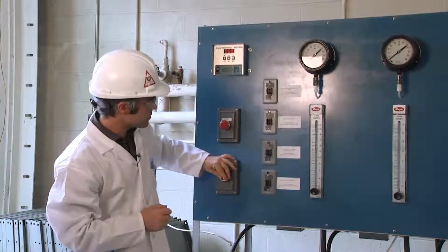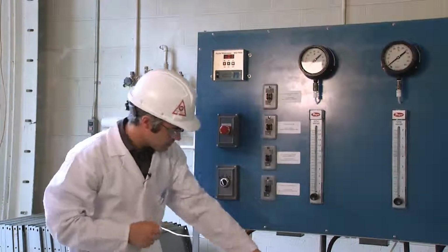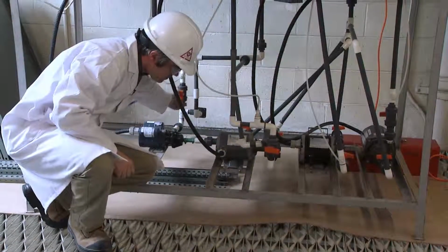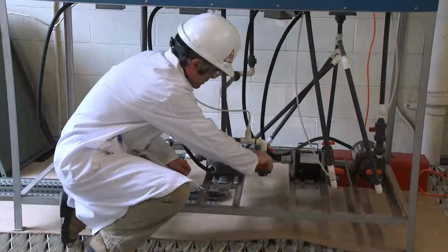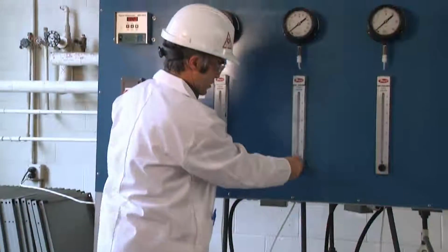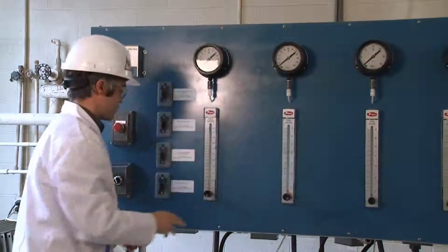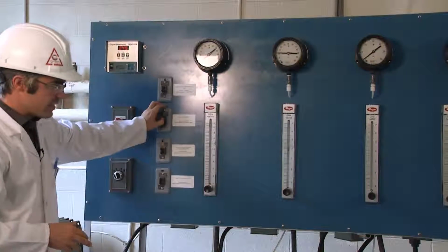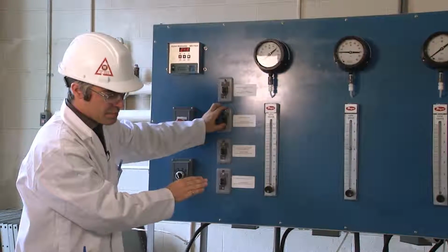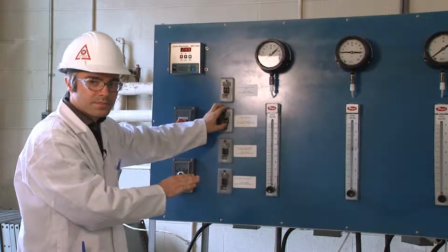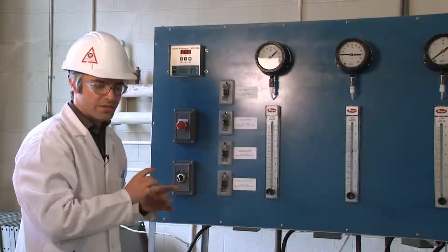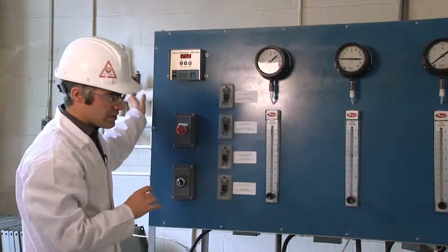For the second pump, we will select the second pump accordingly, close the valves to the screw pump, open the valves to the gear pump, ensure that the rotameter is slightly opened, and we can begin the flow through the apparatus. Now this pump is again a fixed volume, positive displacement pump. We are pushing through, via gears, a set volume of liquid depending upon the speed that the gears are turning.